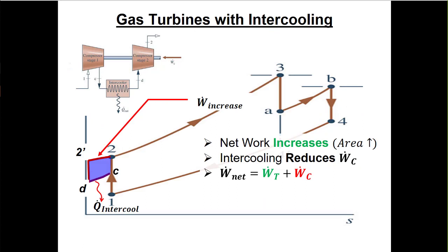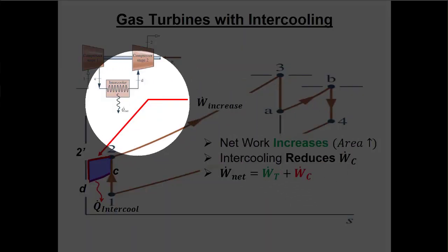Doing reheat, it increases the work we have by producing more power, right? So that's how it increases net work. But in Brayton cycles, because the back work ratios are reasonably high, especially compared to something like a Rankine cycle, we can also improve our net power by reducing the amount of power we put into the system, right? To do this, we add cooling.